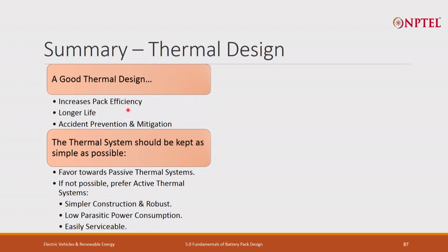Wherever possible, utilize a passive thermal management system because it does not take any energy from the pack. If not possible or it does not help in saving the cost because of the battery degradation, then an active thermal management system, but then again it should be simple.